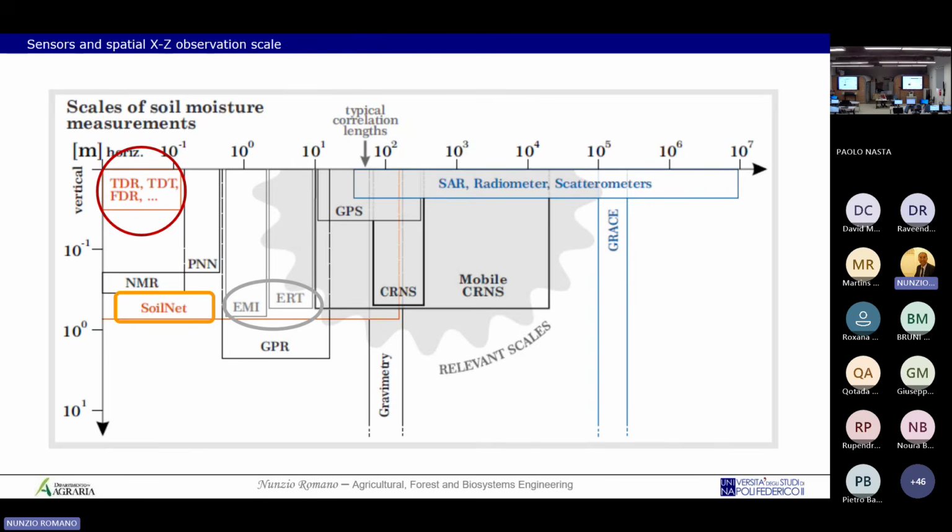But the lower boundary condition below the root zone, below 1 meter, 2 meters, is difficult. Do you have a bedrock or a free drainage? It's different. And the geophysical survey can help you to identify the lower boundary condition as well as possible.